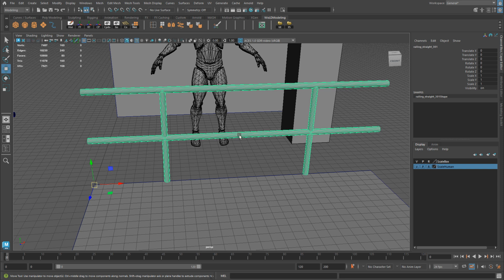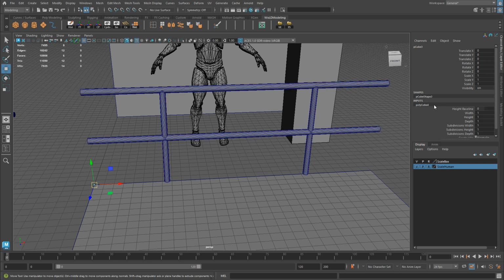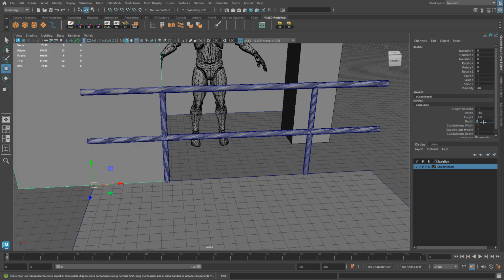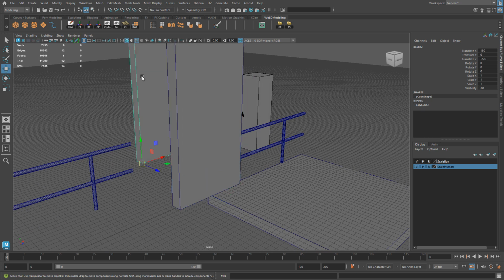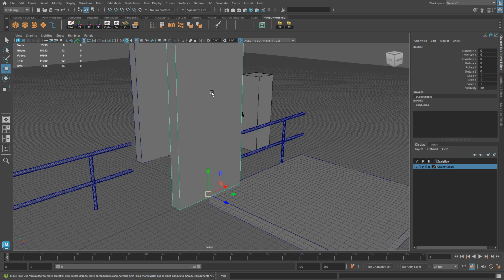To make sure the measurements are correct, I can introduce a 150 floor or a wall just so we gauge the width correctly. So let me introduce a new cube. Height baseline -1, so it's on top of the grid. Width 150, height, let's do 300, and depth at 20. Again, this would be the standard size of a half wall. So we would have a 300 wall and then a 150 wall, and they would match and be seamless next to each other for those spaces that we need slightly smaller.